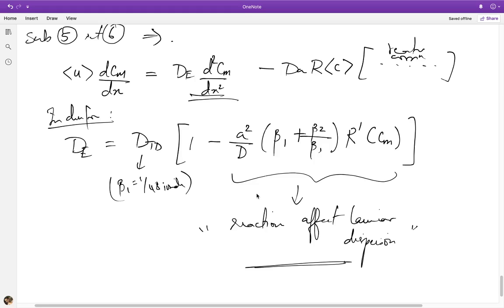So I think that's another important point. Still, mostly people use RTD data in the absence of reaction to size reactors and to use it in the presence of reaction, which is strictly incorrect as seen here. But it's often hard to do these experiments under reaction rate settings, and it's not easy to obtain models that give you that correction. But what this lecture shows is that if you use systematic averaging along with perturbation methods, you can actually derive these results in a rigorous systematic manner.